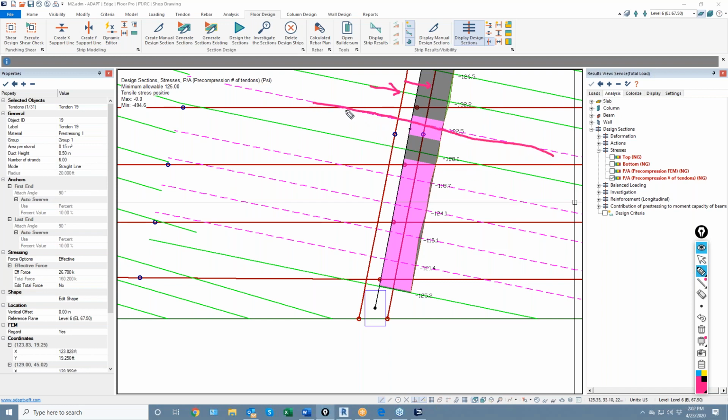But you also have a little bit of force from this cable that intersects it at some very shallow angle. So any tendon that intersects that section, there is an initialization range where if the tendon, I think, is less than 30 degrees, it would not consider the cable. I'd have to go back and check that. But some of these cables may be considered based on their orientation relative to these design cuts.